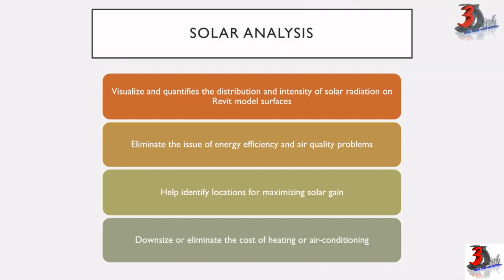Okay, this is something that is available in Revit, where you can actually visualize the sun path and shadow that a site or building element generates during a specific time. So you can also generate an animated study or a still image. The next one, we have our solar analysis. So this is what we're going to do.